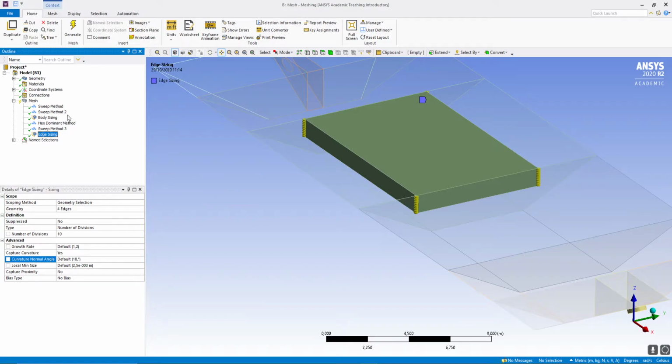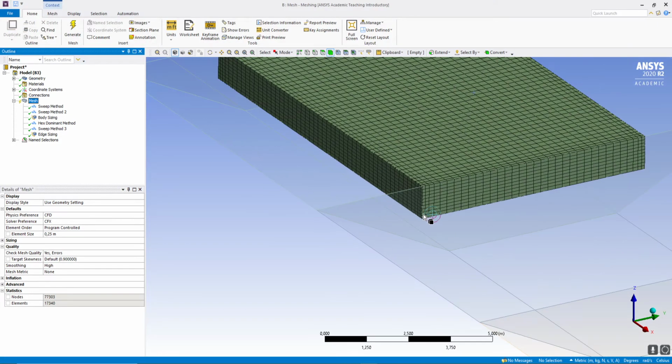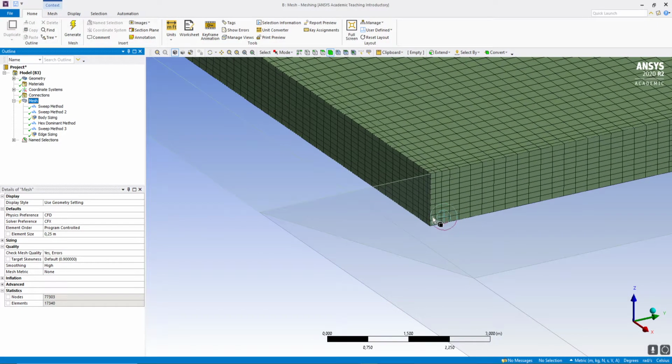and let me show you now how different this mesh will look. You can already see that it takes a little bit longer because it's a more refined mesh. And there you go, 1, 2, 3, 4, 5, 6, 7, 8, 9, 10 elements now in our vertical region instead of only 4. All right,